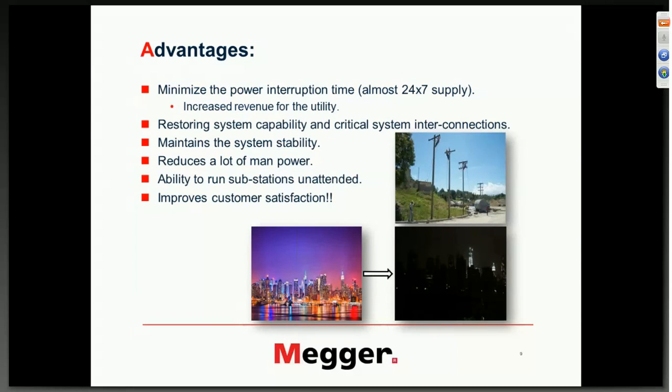I'm going to talk about some of the advantages of having a recloser in your system. First thing is, yes, it does minimize the power interruption time. Whenever there is a momentary fault, you automatically close the circuit breakers, and the system becomes normal again.